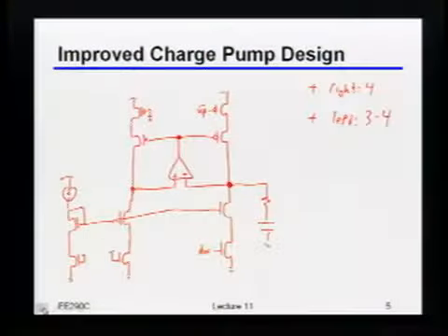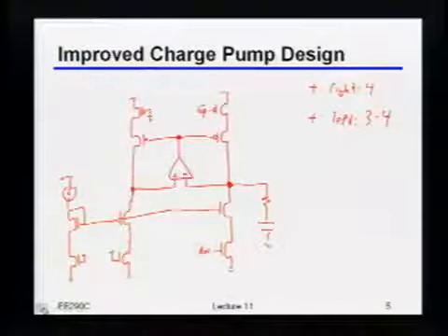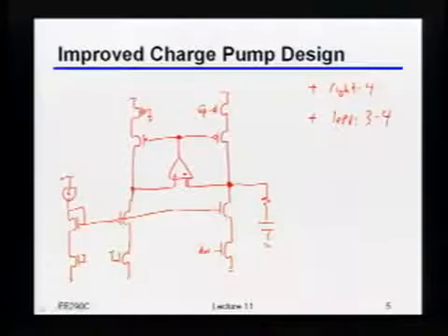Oh, yeah. A question on the previous slide. Sure. So on the bandwidth of the op-amp, is there any constraint on that? Okay, it's a good question. It depends on how precise you want to be. To zero order, you don't have to have super high bandwidth here, only because you know that the control voltage is moving very slowly, relatively speaking.